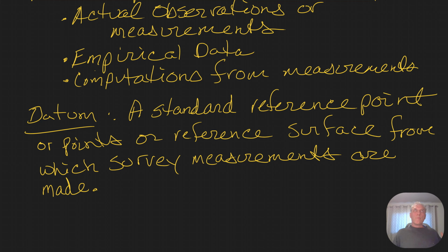So in short, that's exactly what we've just discovered, is that a datum is all of the parameters of the mathematical models, the ellipsoid or Earth-centered Earth-fixed systems, all of that information together with actual observations made in a region or across a certain area like the United States or North America. And then also, I would say, includes physical infrastructure.